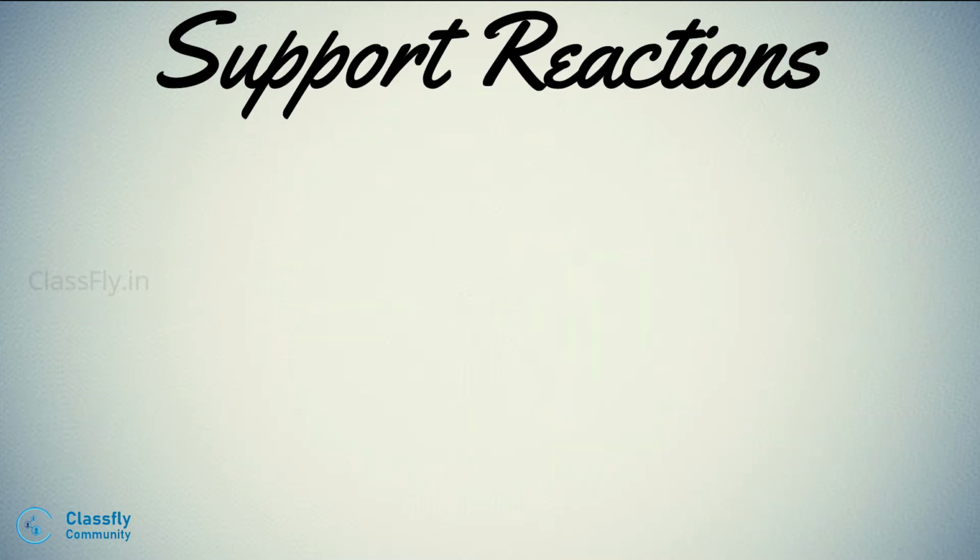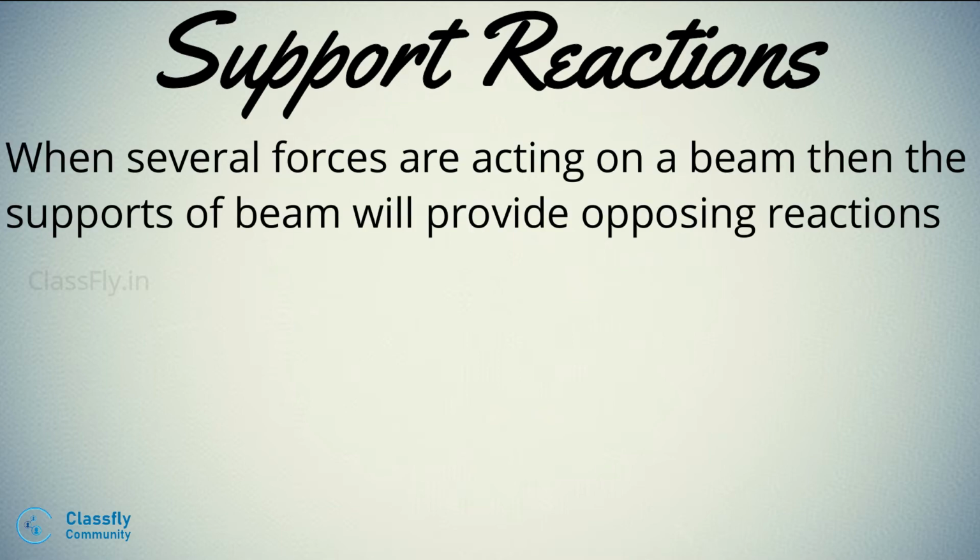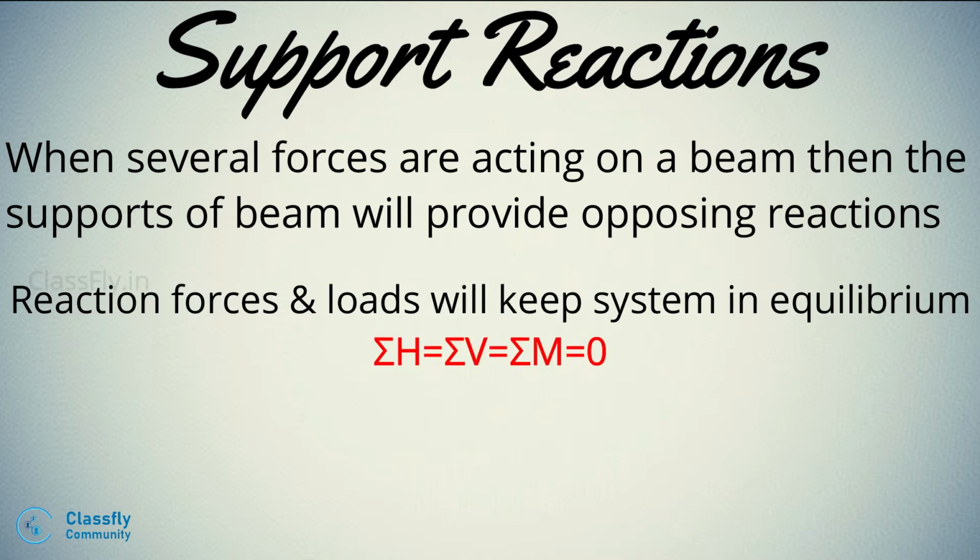Next, support reactions. Well, when a number of forces are acting on a beam, then the supports of the beam will provide an opposite reaction which is called the support reaction. Hence, the reactions provided by the supports along with the loads will keep the system in equilibrium. Hence, here also summation H equals summation V equals summation M equals 0.